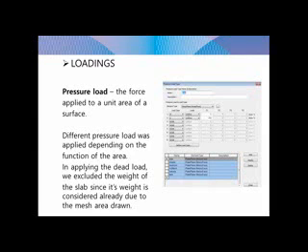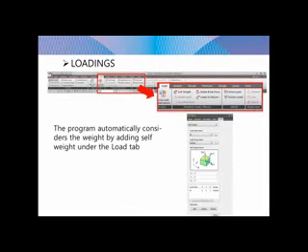Well, in our previous program, to change the load value, you had to select the plate you want to edit and enter the load value again into the command. While in MIDAS 10, editing the pressure load is so easy. Just change the value in the pressure load type and then press modify.